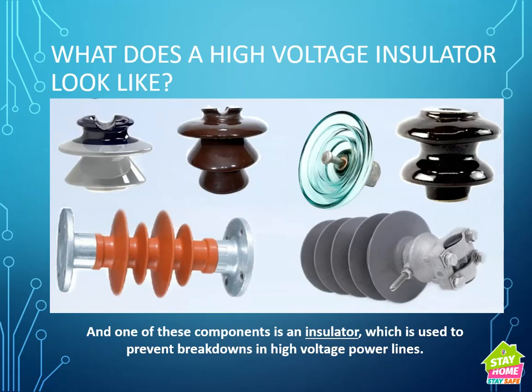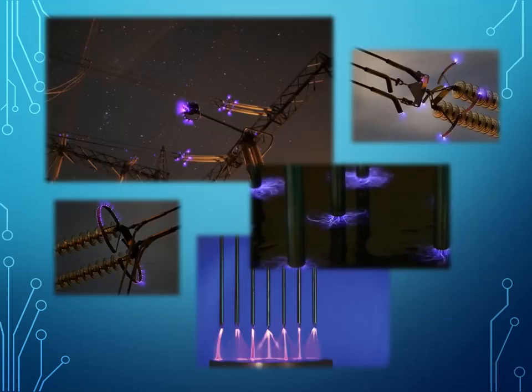Alternating and impulse voltage are distributed unevenly across the insulators of the garland. If you do not take special measures on high-voltage lines of 200 kV and more, part of the insulators in the garland can be so much energized that even under the operating voltage and normal atmospheric conditions, they will form corona discharges, which is a source of radio interference, cause accelerated corrosion of fixtures and will cause additional energy loss.